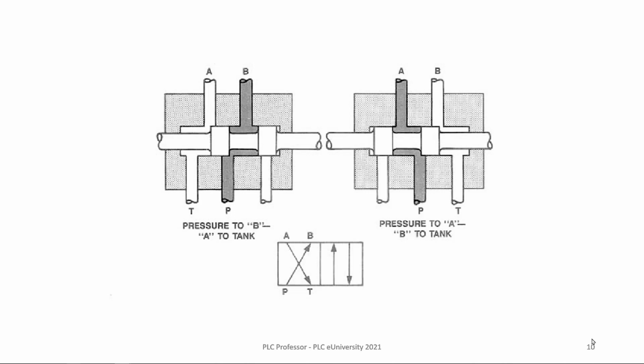And on a hydraulic system, you don't dump the exhausted hydraulic fluid out onto the floor. It goes back to the reservoir. But with an air system, it goes out the exhaust and joins the atmosphere and all its buddies out there in airland. Okay? So T really could be exhaust, or you could say reservoir if you want to look at all the airspace around you as the reservoir.